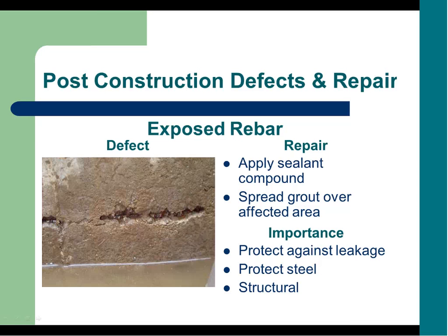Post-construction defects and repair, so exposed rebar. Again, we're going to either apply a sealant compound or a grout over for the same reasons, structurally to protect that steel and against leakage.